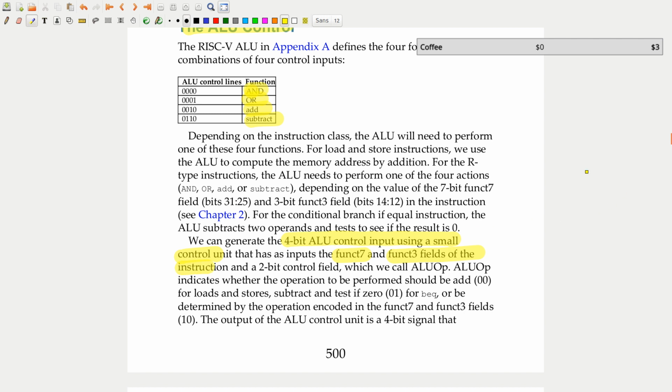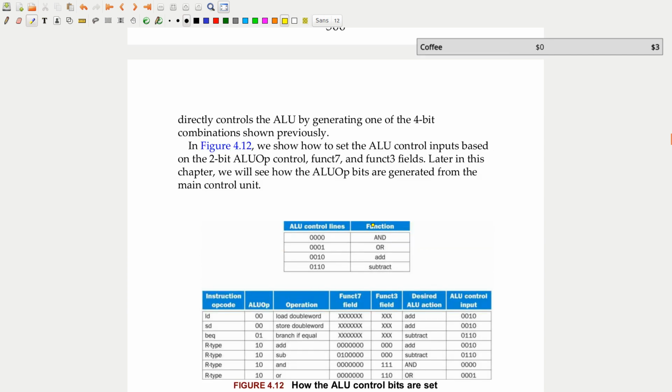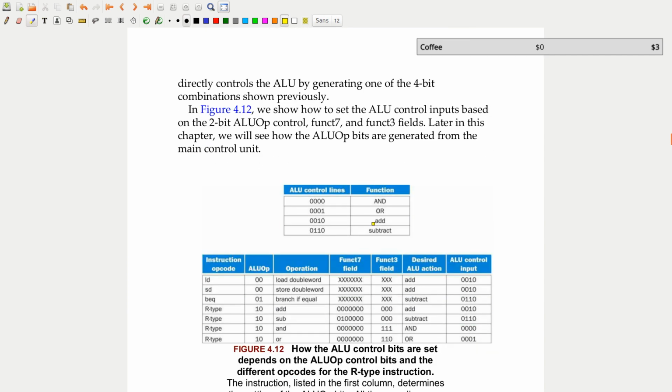So if you remember from the previous time when we talked about all the different fields, we saw that there are fields for registers, there are fields for immediate values within the instruction. We see that we can also embed the operation in here. So for things like loads and stores and branches, this func7 or function7 field can be any value because it's ignored.